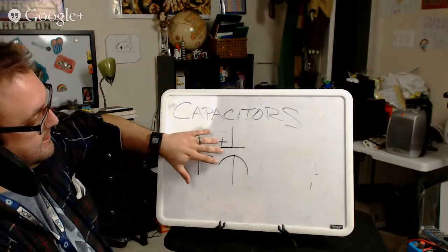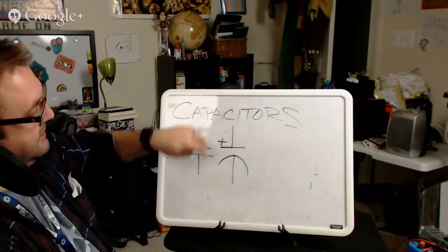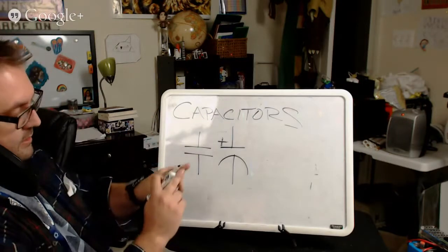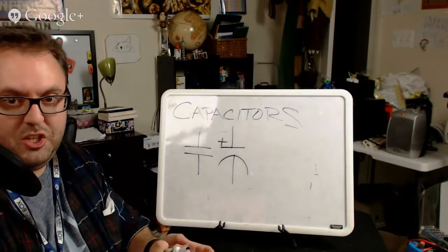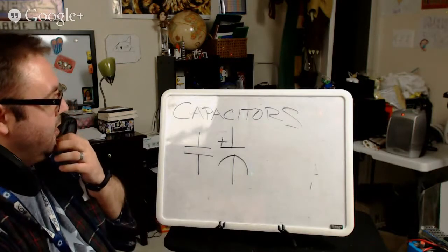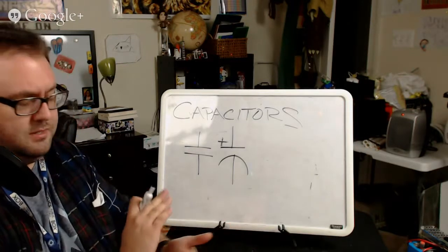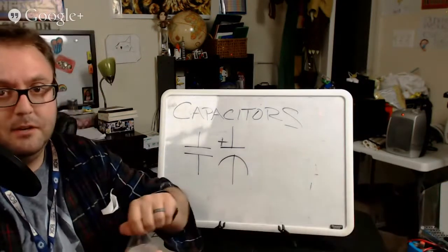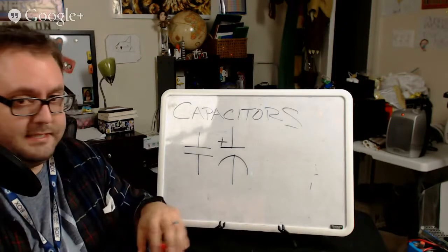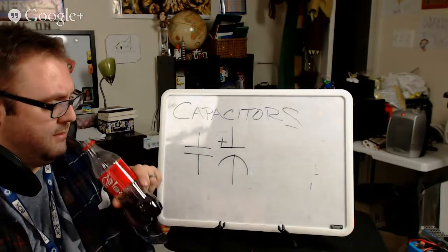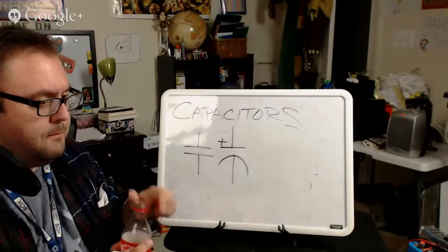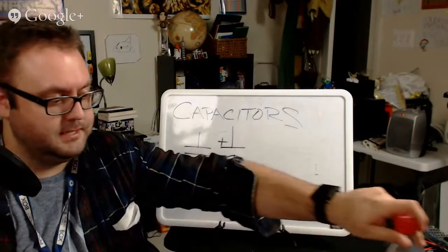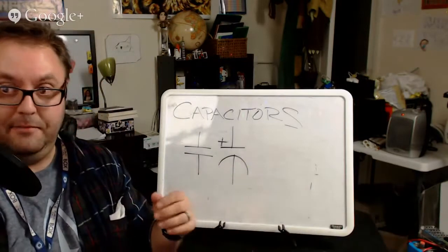A lot of times your electrolytics, the big blue caps, are polarized, and the little ceramic, orange, yellow disc-looking things are non-polarized. Just like there are different manufacturing techniques for resistors, there are different manufacturing techniques for capacitors, but we'll save that for another day. Different capacitors have different characteristics that may or may not be advantageous for your circuit.